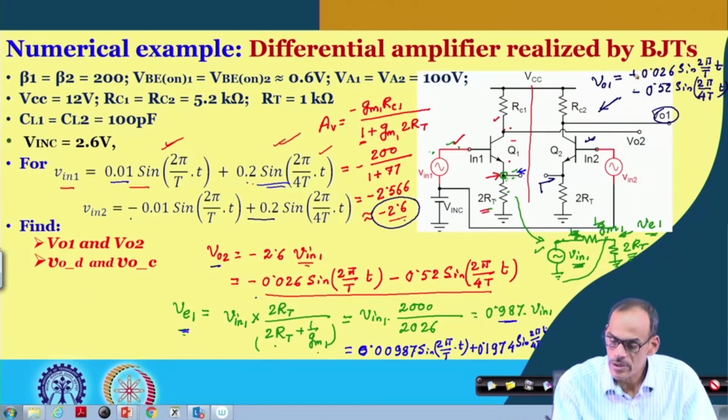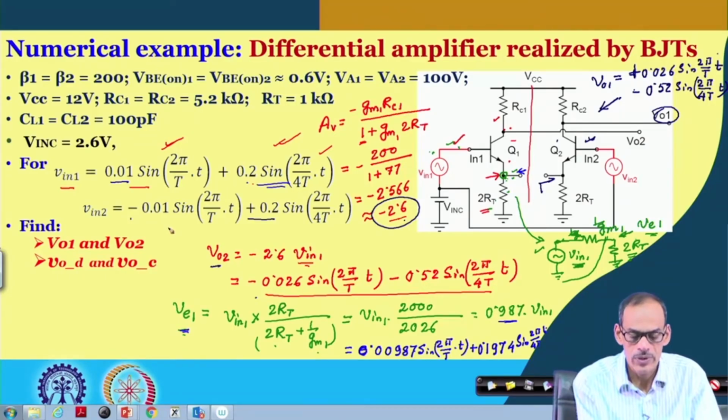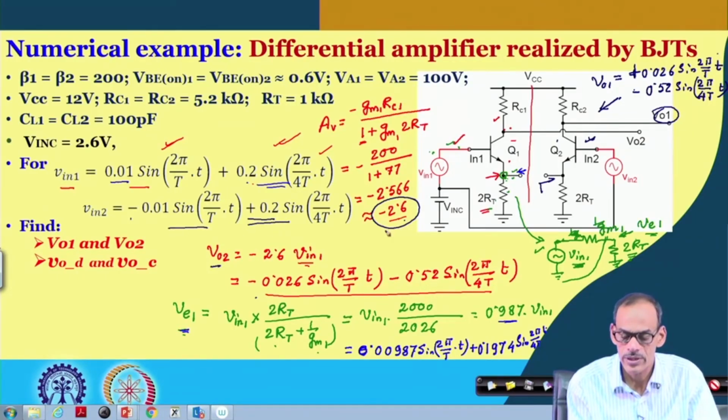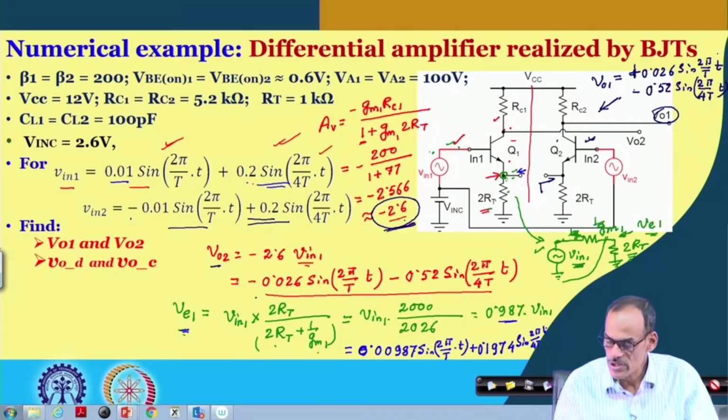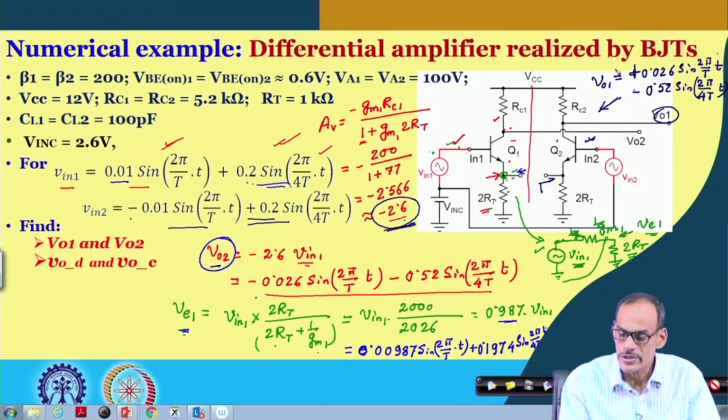So, we do have the two frequencies. Again, this amplifier does not really understand the common mode part and differential part. So, both of these parts are getting amplified by the same gain. If I see the individual signals, this and this, of course, each has both frequency components, and if you are keeping this node still open, and you consider the differential output,